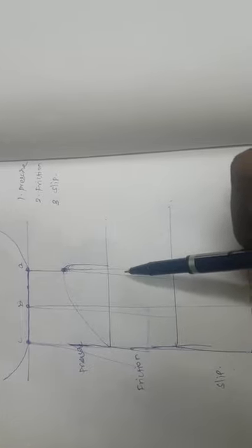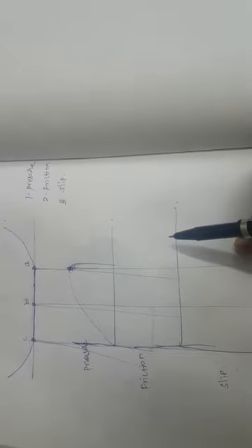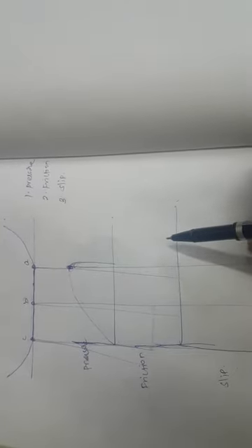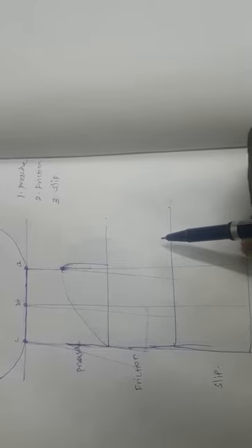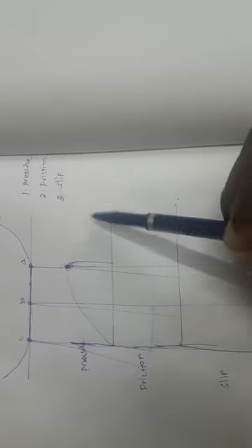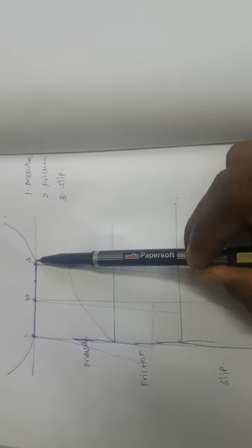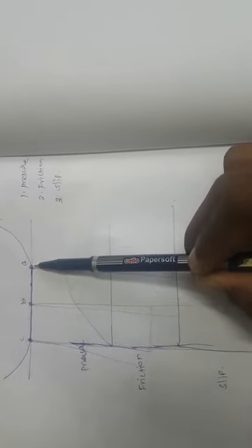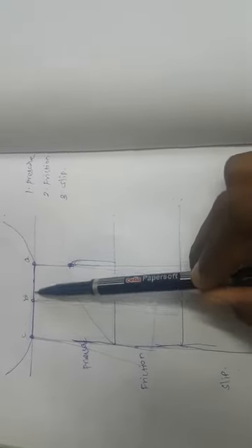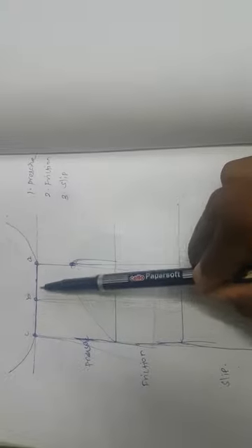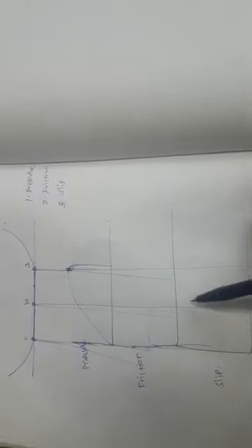Okay. So the tread element proceeds back through the contact patch. Its deflection builds up concurrently with vertical load and it develops even more friction force. If the contact patch approaches the center, the friction will be more at this point compared with other points.